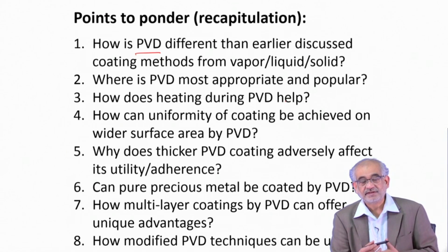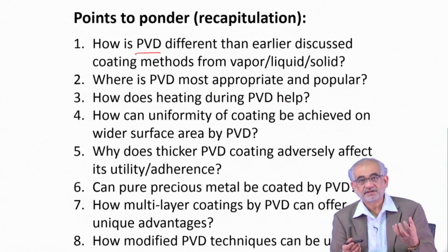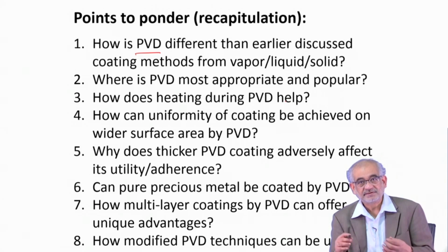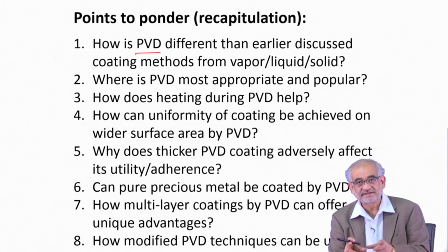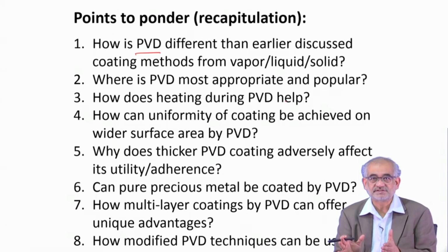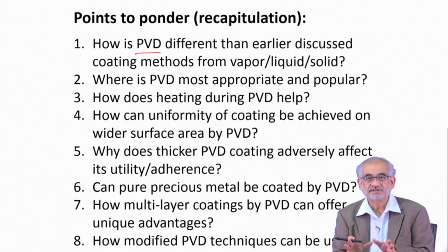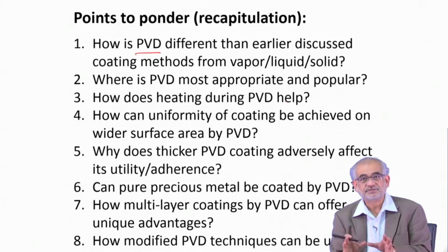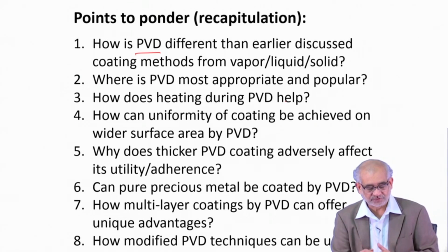In fact, we can make a non-stoichiometric alloy and rapidly solidify it, or simply blend different types of powders, crush them, mill them, and then sinter them together, create a target with the right composition, and use that as our target for deposition. So we are then able to deposit a very new and exotic, non-stoichiometric composition onto the component that we want to coat.